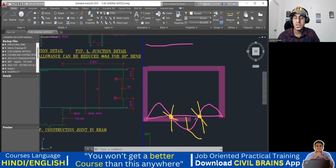When you start your next concreting, this particular point will become your weak point. The moment it is a weak point, of course, this particular point is subjected to higher moment. There may be a chance of small cracks and a kind of small failure. Failure in the sense doesn't mean that the complete beam will fall. That usually doesn't happen. Small cracks may come. So in order to take care of that, the code, or the general drawing, says that you have to plan in such a way that wherever there is a point of contraflexion, there you stop your concreting.